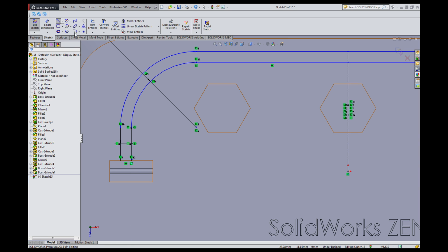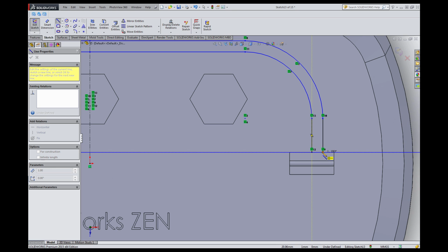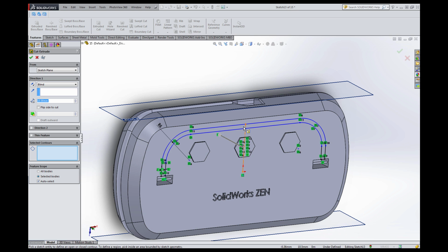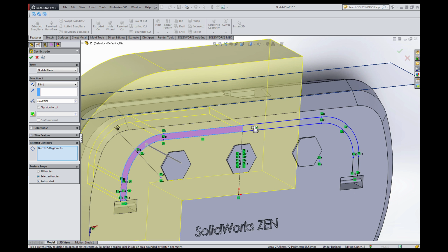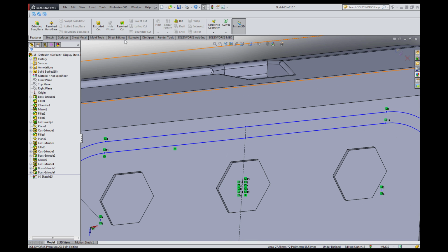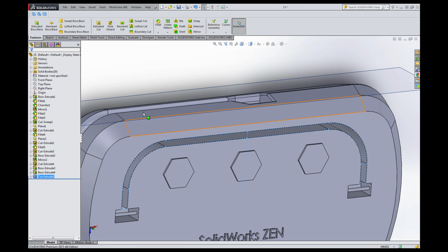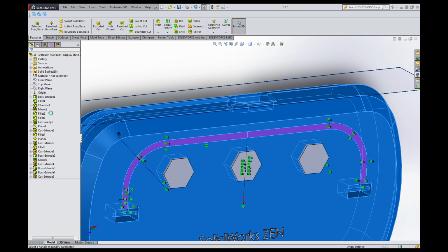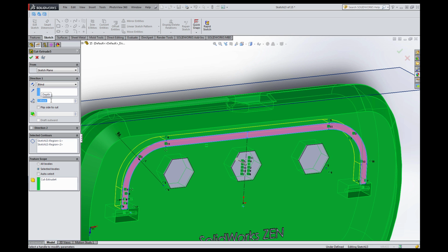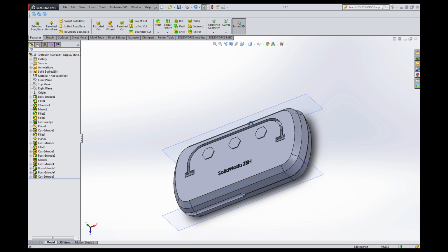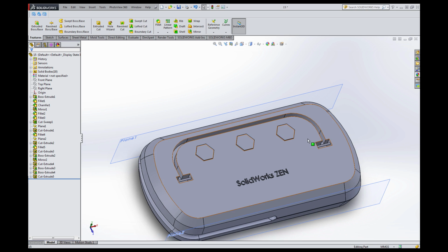Okay, like that. Now I can use the extrude cut option and I can cut this profile. Okay, I want to extrude cut this profile right here and another one, this one right here. Okay, I have two selections and I'm going to confirm. Sorry, go back, edit feature, not 10mm but rather 2mm. Okay, 2mm. Okay, this is the slot where the handle will be placed.